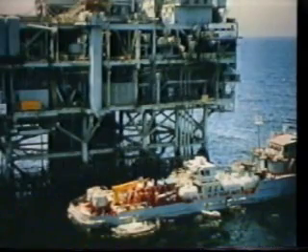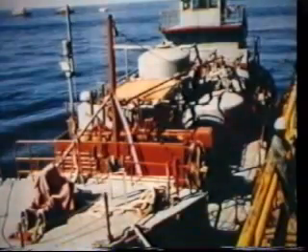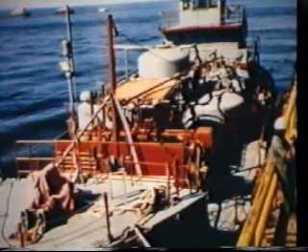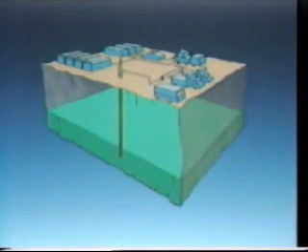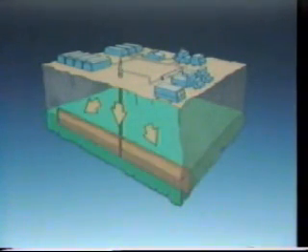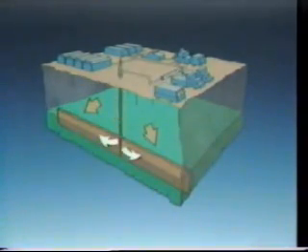If the acid is pumped at a pressure great enough to fracture or split open the rock, it becomes an acid fracture treatment. Fracturing in general is another form of stimulation used to create flow passages in a rock where none or few exist. In hydraulic fracturing, a fluid is pumped down the well bore at pressure sufficient to cause the rock to split apart, usually vertically, allowing the fracturing fluid to enter.